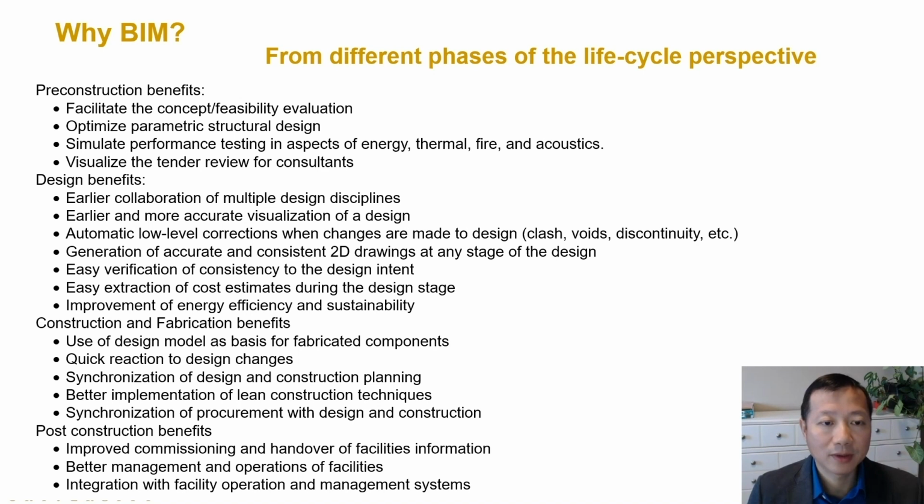During the design phase, as it is a neutral collaboration platform, it enables earlier collaboration of multiple design disciplines, and allows you to visualize your design in an earlier and more accurate mode. It allows automatic low-level corrections when changes are made to design, such as clashes, voids, and discontinuities. Also, the generation of accurate and consistent 2D drawings at any stage of the design, because we are always looking at a single central database.